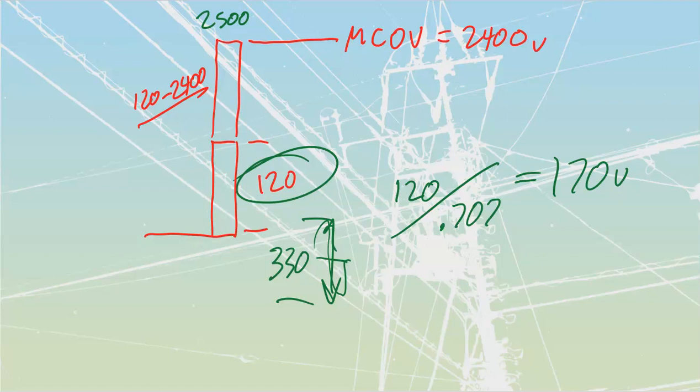Now, if I have something that's got a 40 kiloamp let through, all it means is it's got more paths inside. They're just placing more parallel elements inside of it, so it can do that more often. It's not going to burn out nearly as quickly. Short circuit current rating is going to be the maximum size of my short circuit current that the component or assembly can withstand.